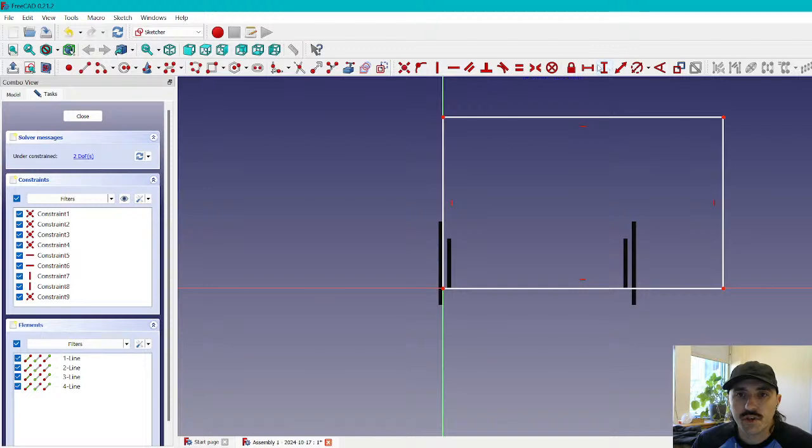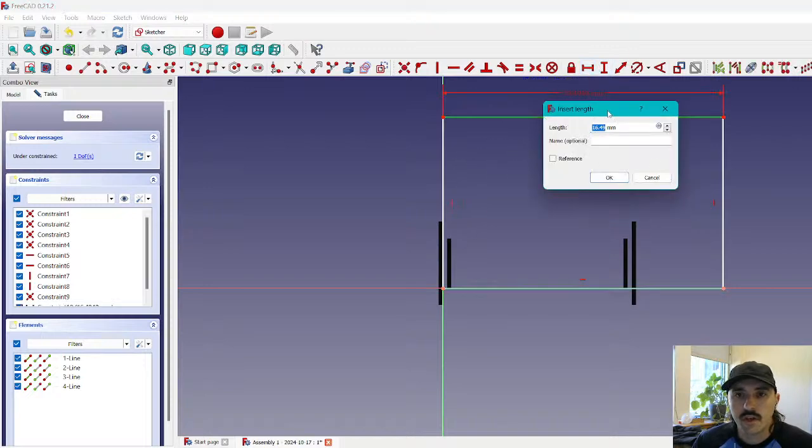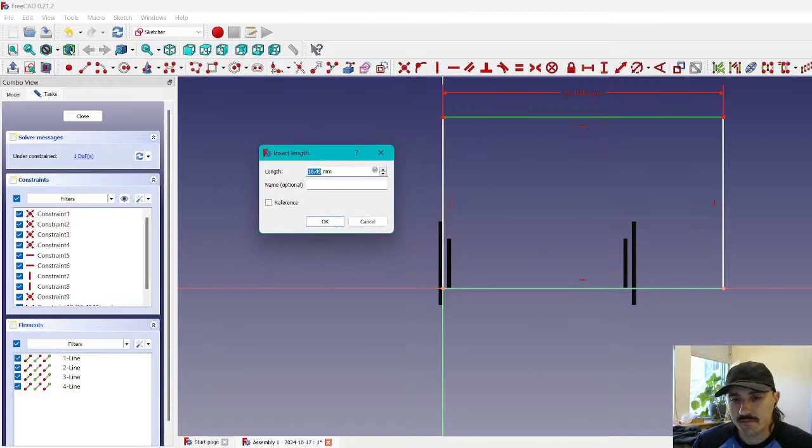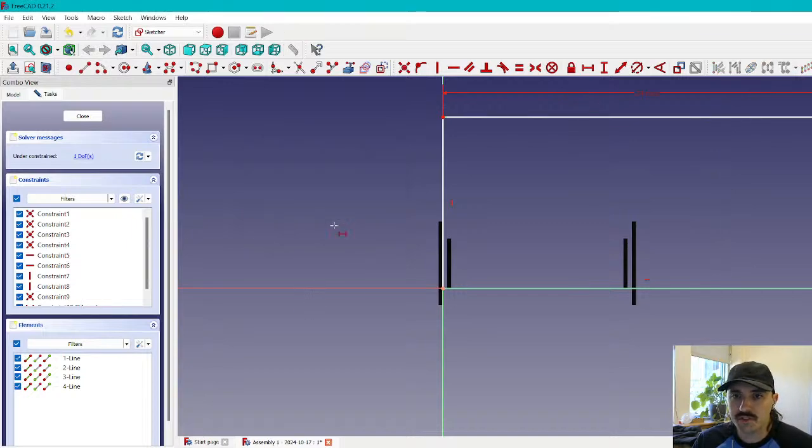So then the next constraint we're going to offer is width. STL files are unitless. There's just numbers. They get imported as millimeters. However, that's designed in inches, so this is ultimately going to be a 24-inch by 12-inch sheet of plastic this will be cut out of. But for now, we simply understand that 24 millimeters is equivalent.